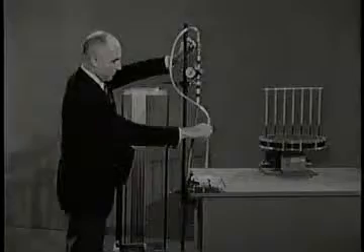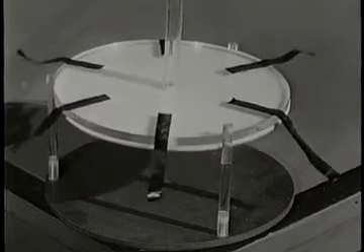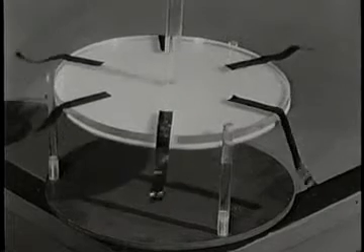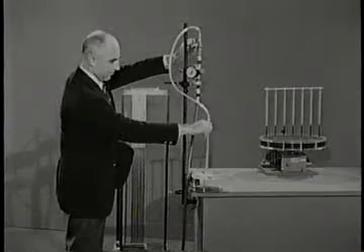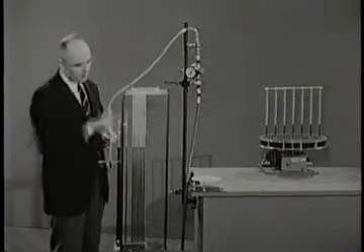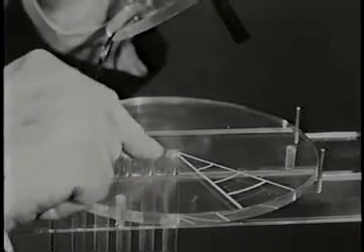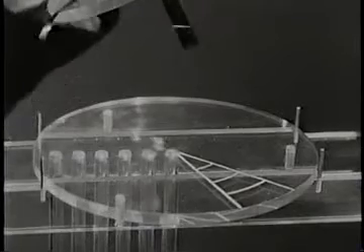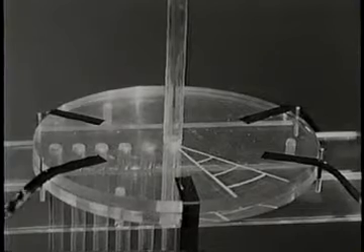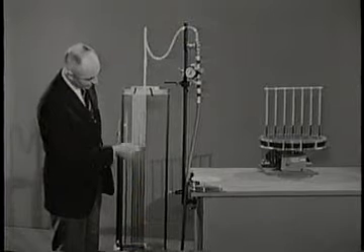Air from a hole in the middle of the upper disc is blowing against the disc below. To see how we could lift that plastic disc by blowing against it, we've instrumented this plate with pressure taps attached to manometer tubes below. Three little spacers keep the disc and plate apart. This open tube shows atmospheric pressure. In these tubes, the water level rises when the pressure goes below atmospheric.